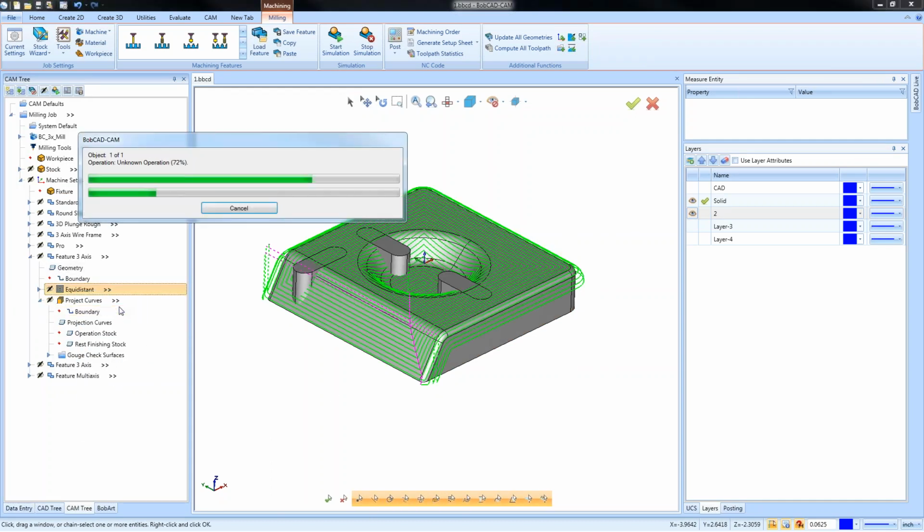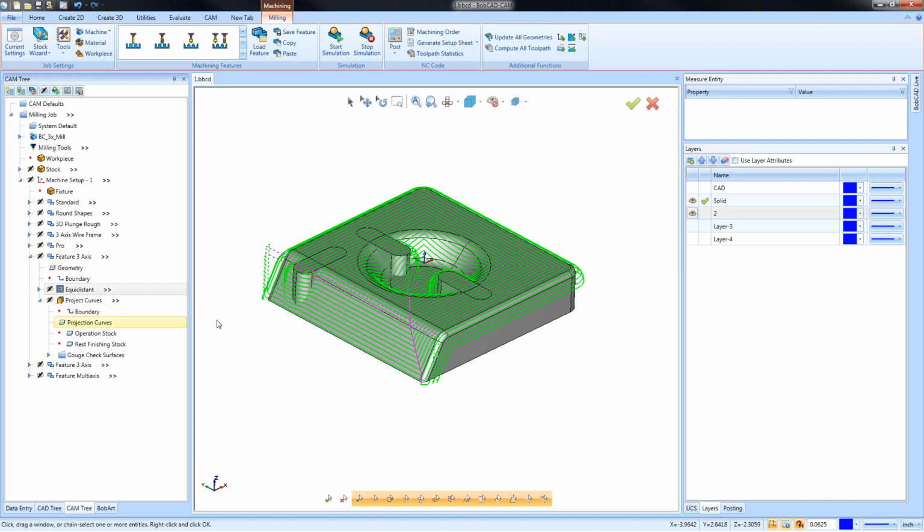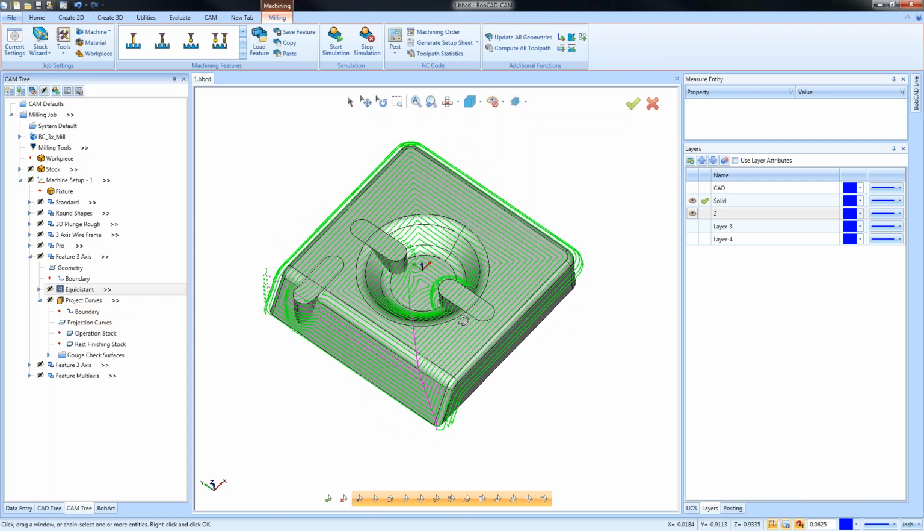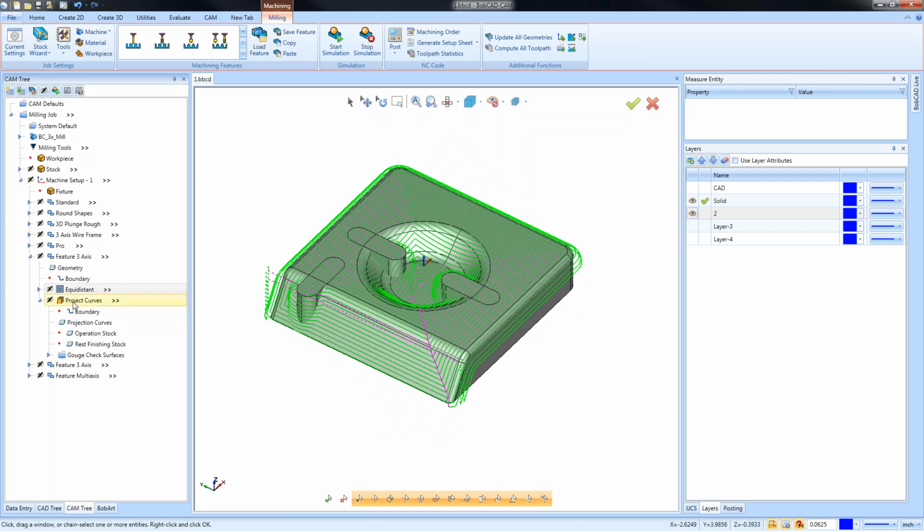And just because it's a good catch-all, it doesn't necessarily mean you want to use it in all scenarios. Because the tool changes direction a lot, it can affect your finish. Again, I use this more as a catch-all or more as a detail type toolpath. And again, just showing you the differences of the different toolpaths here.